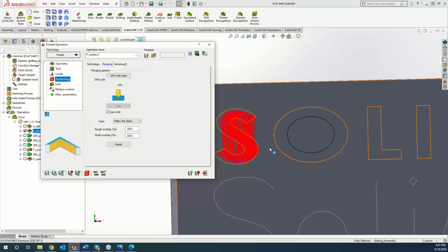For instance, HSS user-defined projection can also be used as a way of doing 3D engraving. Or if we were looking at the other part that Kevin was doing earlier tonight, if you wanted to use your 5-axis to control the tilt angle and still do some 3D engraving, the multi-axis toolpaths would allow you to do that as well.